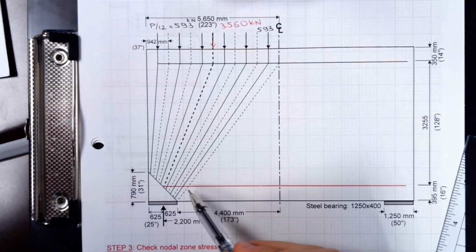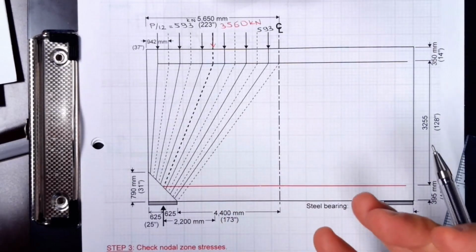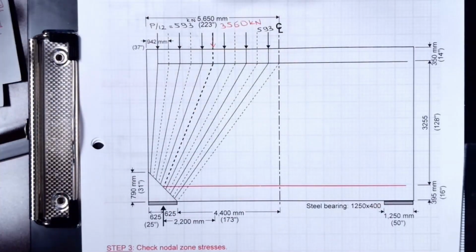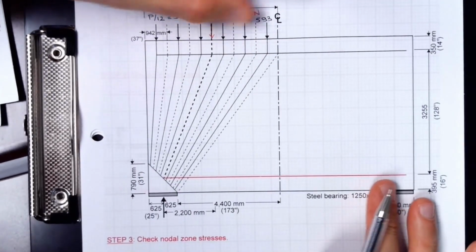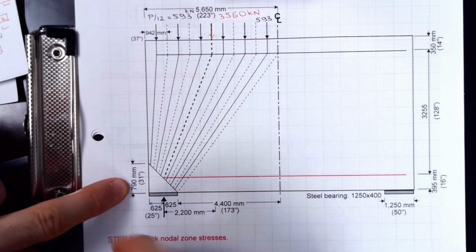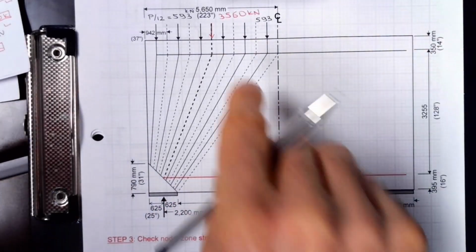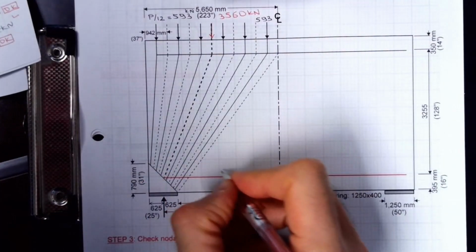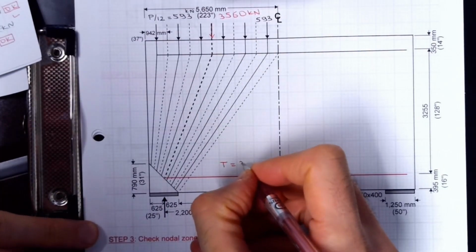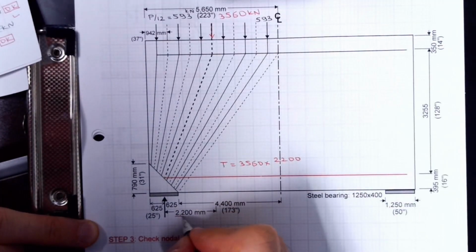The challenge will be to get the angle. If you sketch this in AutoCAD to scale, you are done. But if you are doing hand sketches, you have some trigonometry to do to get that angle. If you do the analysis, you know all dimensions. The tension, you can use the resultant to get the tension. So the tension here is going to be 3560 times 2200, which is this distance,